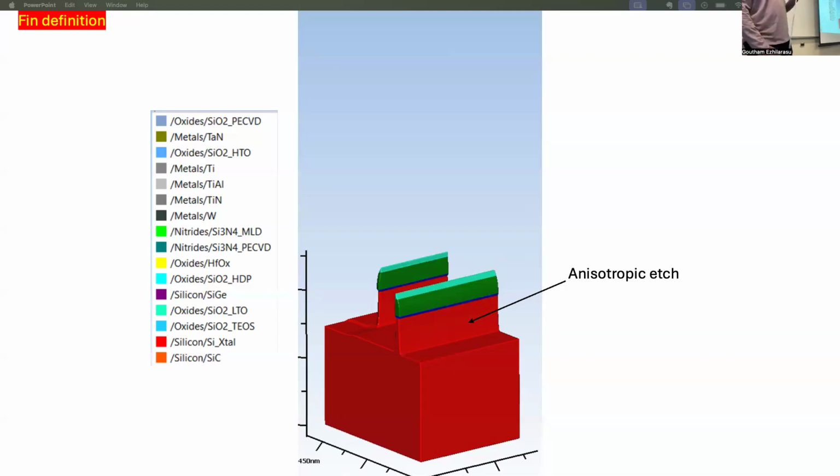To use a sidewall spacer to define the fin, you can't just use photolithography. Someone else also asked me this. Most of these FinFETs were created at a time when EUV didn't exist. With the more primitive lithographic techniques, you can't get sub 20 nanometer features with lithography; it's difficult to do. That's why you use sidewall spacers. For 14 nanometer, it's still done with sidewall spacers.